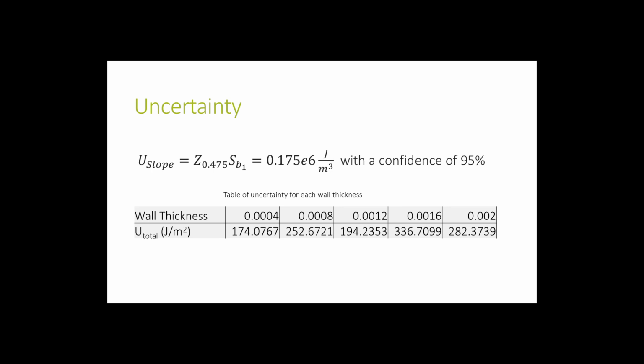To calculate the uncertainty, two different components were used in this experiment: the bias uncertainty and the precision uncertainty. The bias uncertainty was mitigated as much as possible by calibrating the instruments for impact testing before each testing session. This means that we could rely upon the caliper and the impact tester's error to find our bias uncertainty with an error propagation for a 95% confidence.